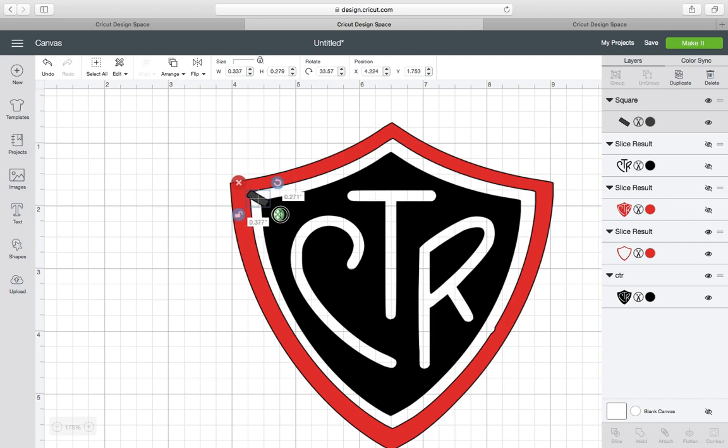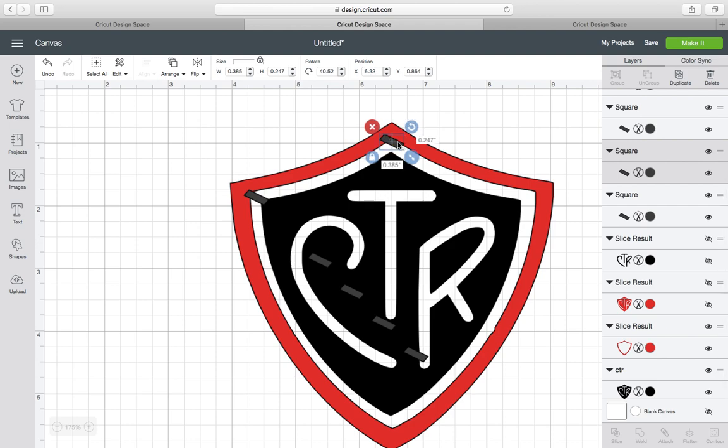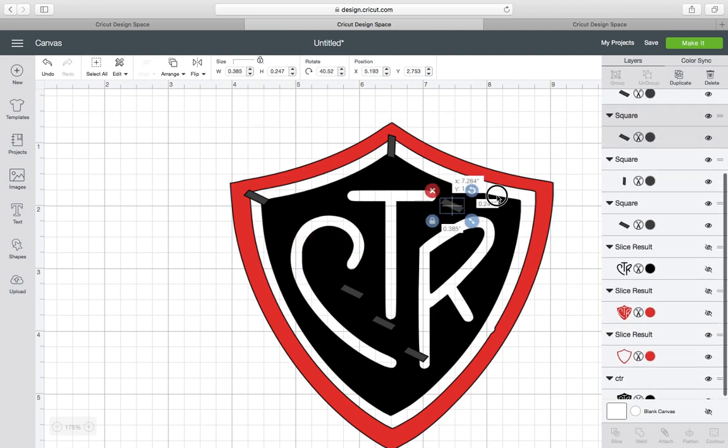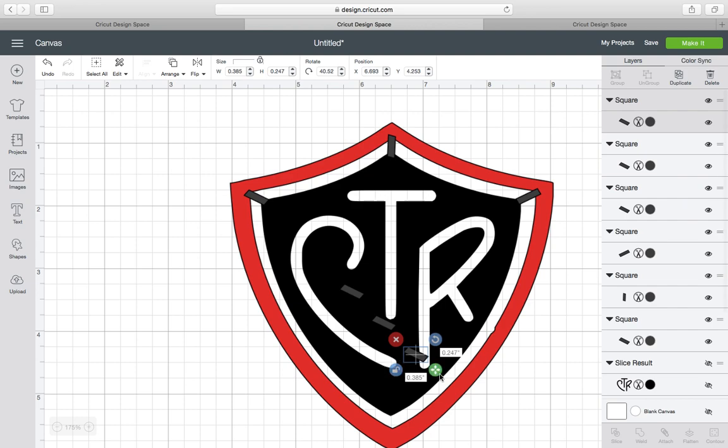I'm going to extend it. I want mine a little skinnier. Okay, so now we're going to duplicate those hinges. We need about 5 of them. 1, 2, 3, 4, 5. Okay, and I'm going to attach it everywhere there needs to be an attachment. The color doesn't matter if it overlaps. It is going to be all welded together in one shape. So here we go. Make sure it does reach both images, and unlock those hinges as well. If you don't unlock them, then you cannot adjust them. That is very important.